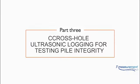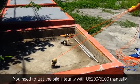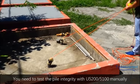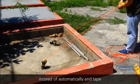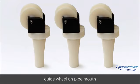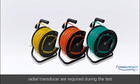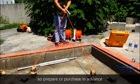Part 3. Cross-hole ultrasonic logging for testing pile integrity. Preparation before test. You need to test the pile integrity with U5100 manually instead of automatically, and tape, guide wheel on pipe mouth, and radio transducer are required during the test, so prepare or purchase in advance.